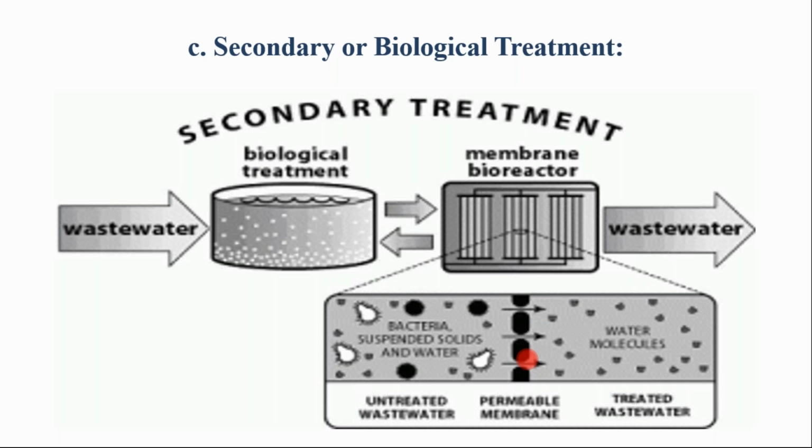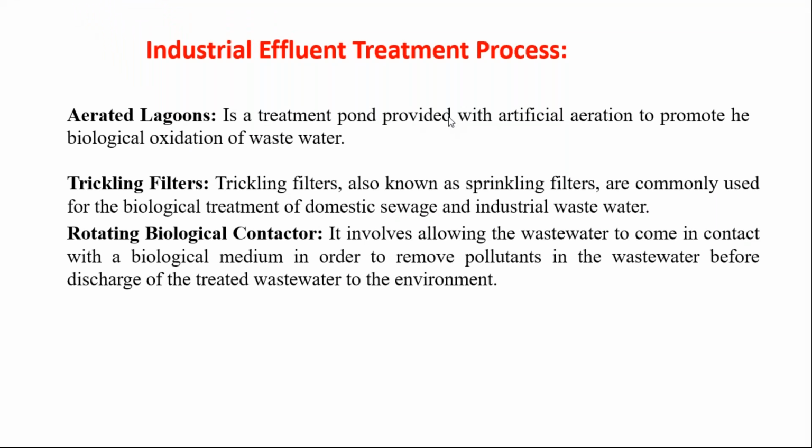Then we can also use aerated lagoons, trickling filters, and RBC, that is rotating biological contactor, under this biological treatment facility. In the aerated lagoons, it is a treatment pond provided with artificial aeration to promote the biological oxidation of wastewater. Now in this biological treatment, we have to keep a record of the dissolved oxygen, because if the dissolved oxygen level is less than 4 mg per liter, then it is harmful to the